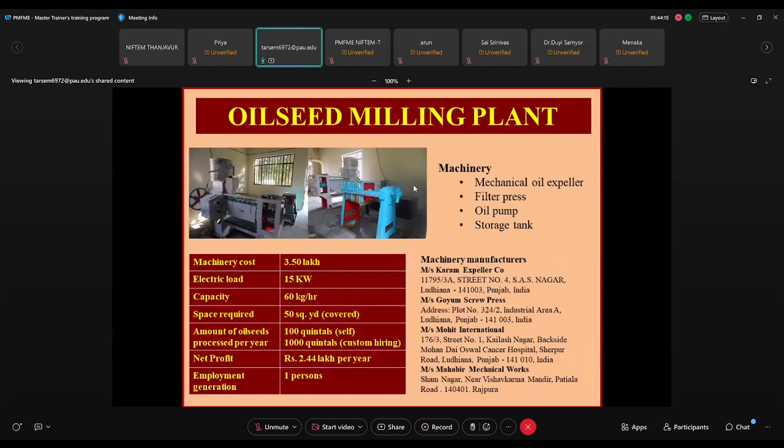Then the third soluble impurity is its odor or its smell. There are certain odor-containing substances in the oil which are soluble in the oil, and they have to be removed by using steam, hot water steam, so that the smell of that oil is removed. Then some gummy material, phospholipids, etc., may be there, which have to be removed.